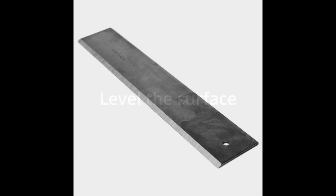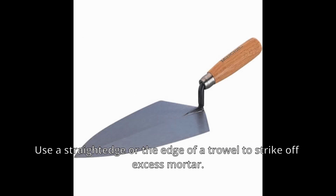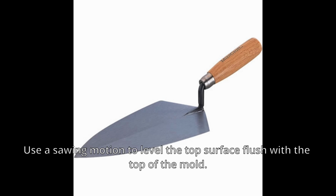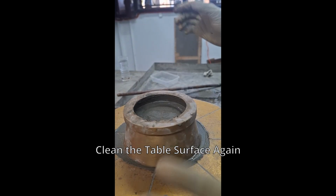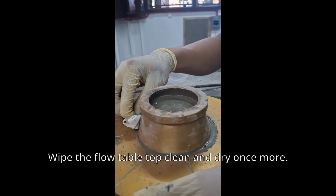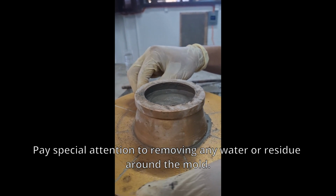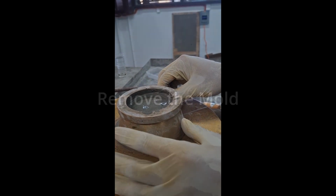Next step is level the surface. Use a straight edge or the edge of a trowel to strike off excess mortar. Use a sawing motion to level the top surface flush with the top of the mold. Next step is clean the table surface again. So wipe the flow table top clean and dry once more. Pay special attention to removing any water or residue around the mold.